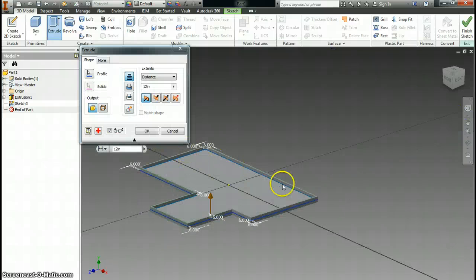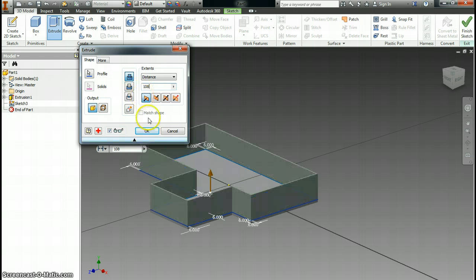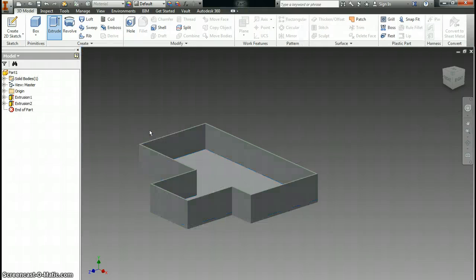Okay, so as you're seeing here, I selected all of the exterior walls, and now I'm going to specify a height. I'm just going to say 9 feet for the height of my walls, which if we enter it in inches is going to be 108 inches. And now you start to see that they are looking like the walls of a house. So I'll say okay to that.